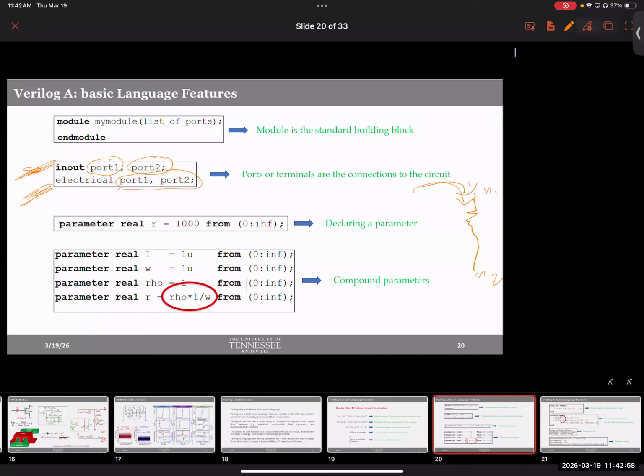Okay, for electrical, imagine I add some extra port 3, port 4, but they don't really exist. They're just virtual ports. Oftentimes, for the sake of modeling, we create virtual ports within the model, which are not supposed to be participating in KCL and KVL formation because they don't exist. They're just helping me do some intermediate calculations. Okay? So if you don't specifically mention that these are not electrical ports, then SPICE will try to solve KCL, KVL in those ports as well. Does that make sense, folks?